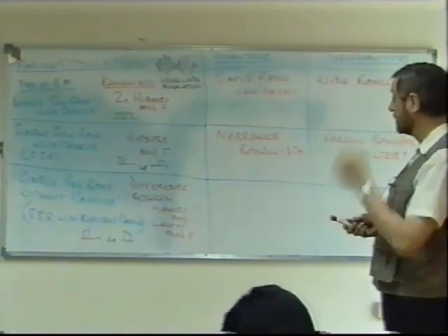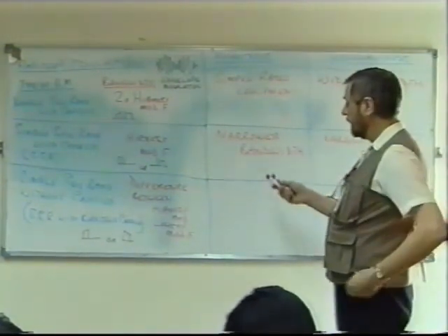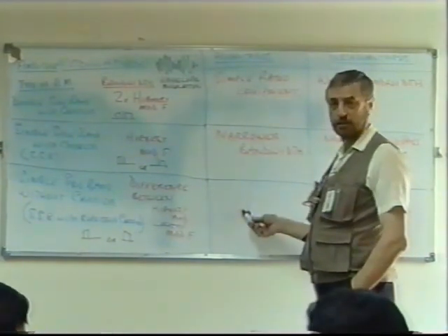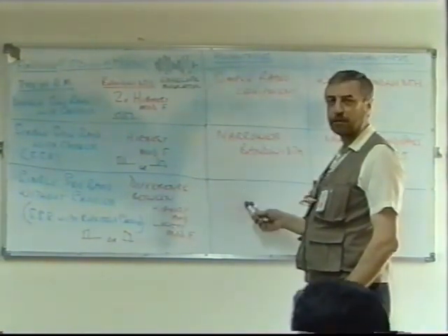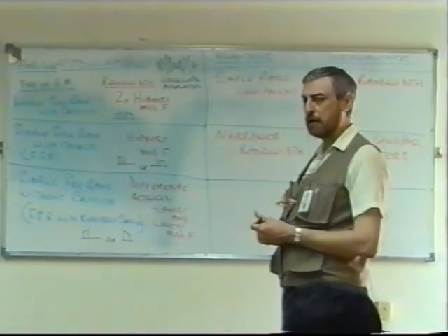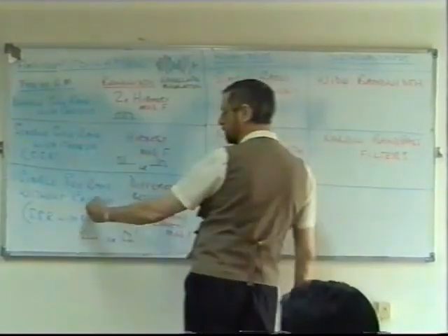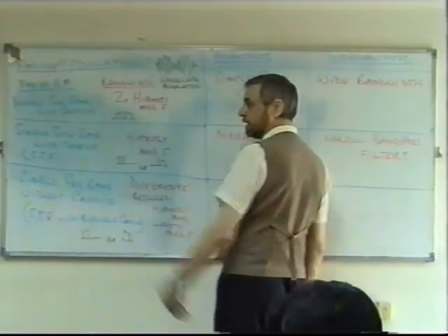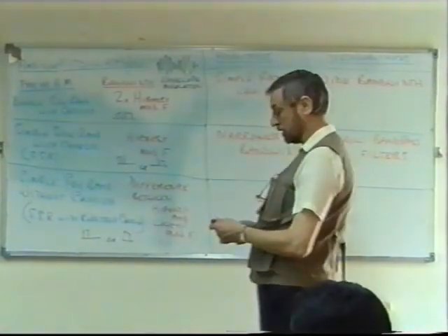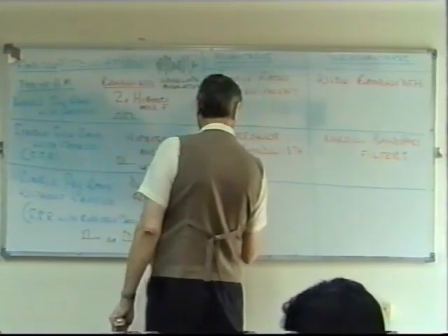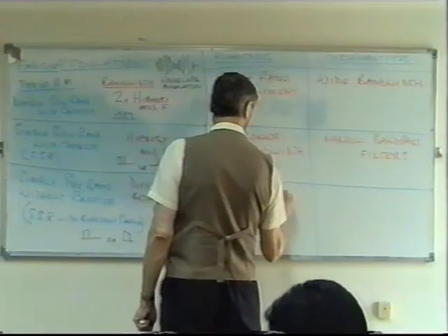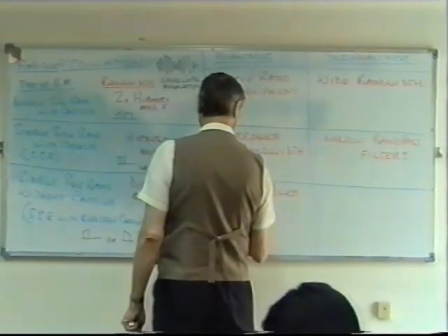And finally, of course, the single sideband without carrier. How much bandwidth is changed depends on the lowest frequency. So there's a little bit of bandwidth saving compared to this, but the main advantage is saving power in the carrier. If we reduce the carrier in our transmitter, the power that's wasted in the carrier can be put into these side frequencies. So it's more efficient. So I'm going to put here: the main advantage, saving power in the carrier.